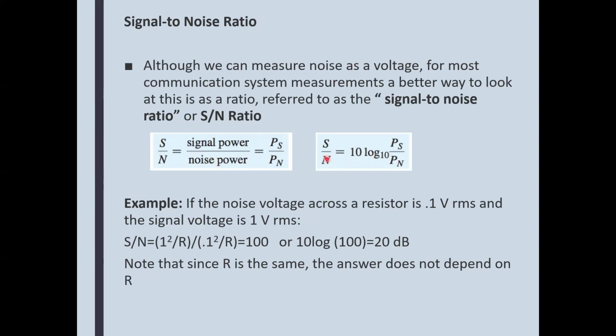Or if you want to get that in dB value, then because we're dealing with power, we're going to apply 10 log, with a base of 10, or sometimes it's not being written here, but this here. If we're dealing with voltage, we'll be applying the 20 log, but we're dealing with power to power. We're dealing with powers. Then here's the 10 that we apply. So if you want to describe the signal to noise ratio in decibels, then this is the formula that you're going to apply.